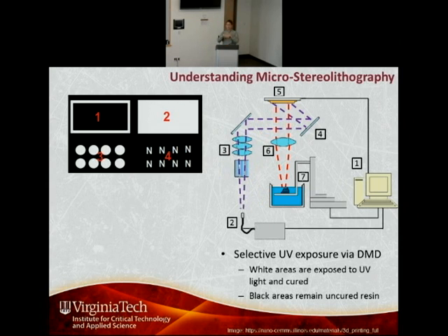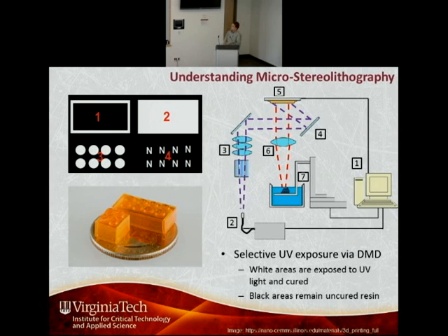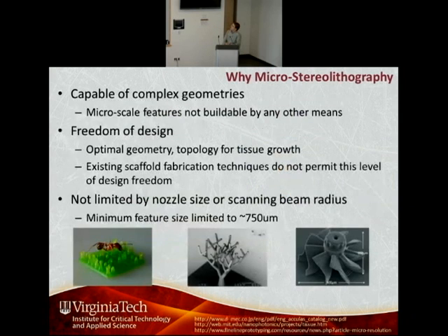This is work from Tim's lab. And so now this is where I start fumbling. The bottom line is that Tim and his lab have generated a biocompatible photocurable resin and have functionalized it to reduce the viscosity, which makes the processing much quicker and easier for us, because as we lower the elevator, the resin level has to settle, and lower viscosity makes that process a lot faster, so it should improve printing time. And again, the key thing, of course, is getting something that's biocompatible, something that cells will survive on.